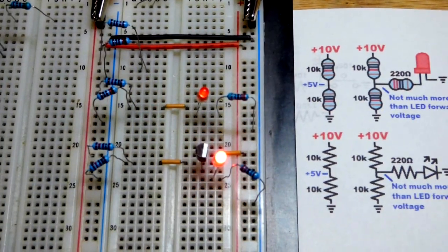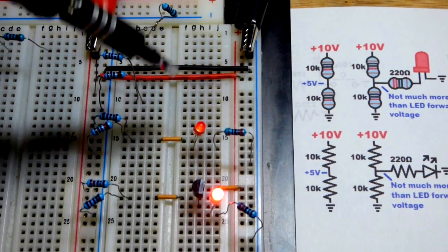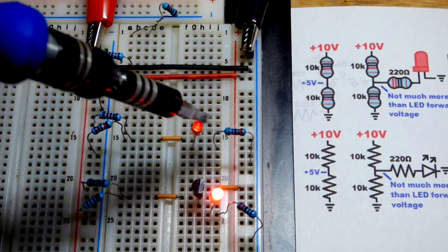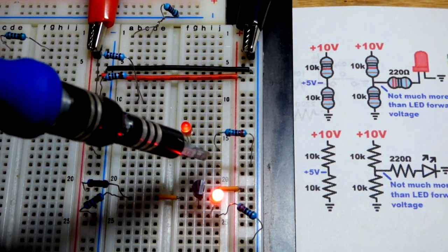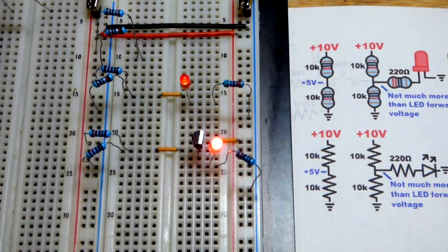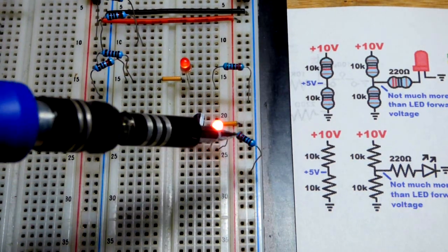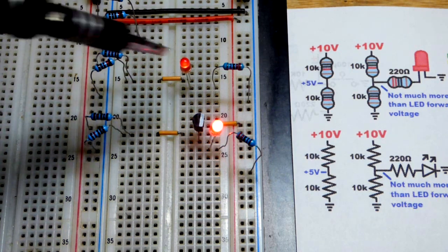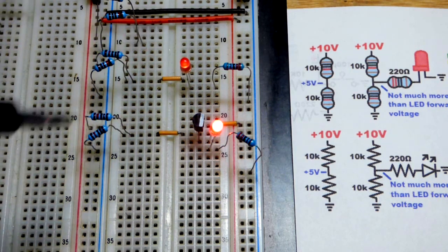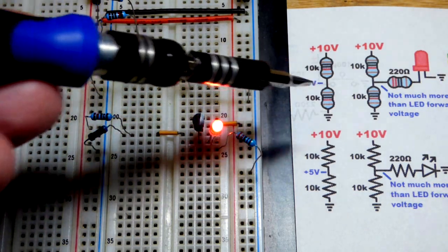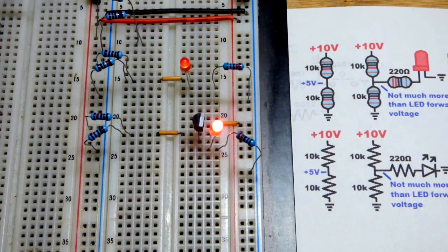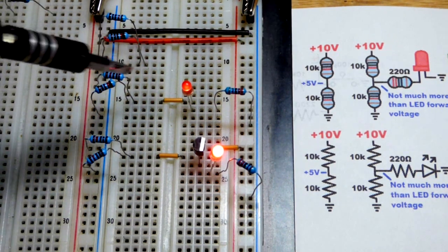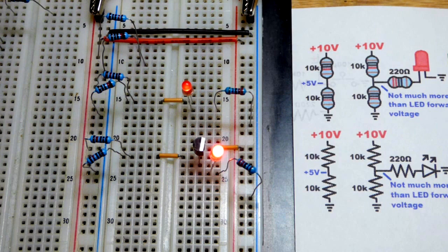As you can see here, we have the fixed resistors up there, two of them. Same thing here, but now we're going to the anode, the long lead of the LED, short lead the cathode, to a 220 ohm resistor. Same resistor that is limiting current for that LED. Problem is, the voltage divider's also limiting current. It has to be able to provide the power, but I'm using all 10 kilo ohm resistors, and not much current can flow through them. They're somewhat high value resistors when it comes to the current you need for an LED.